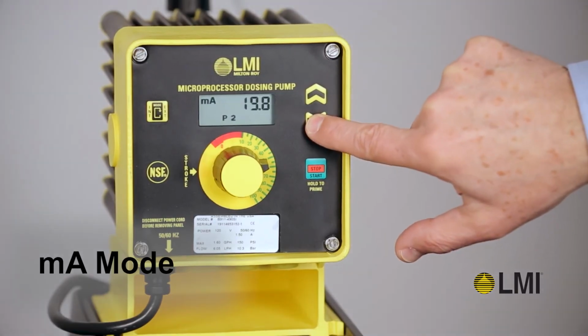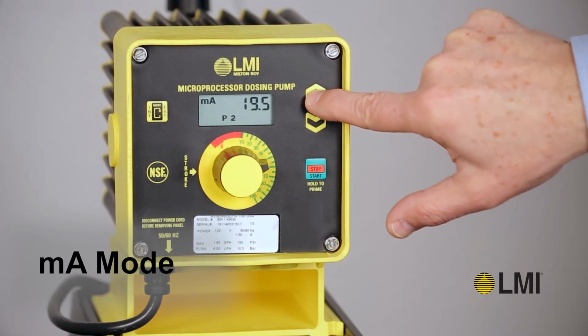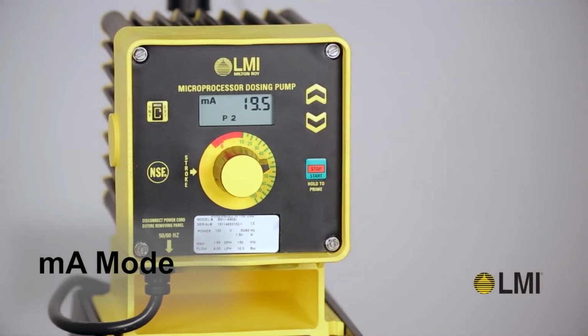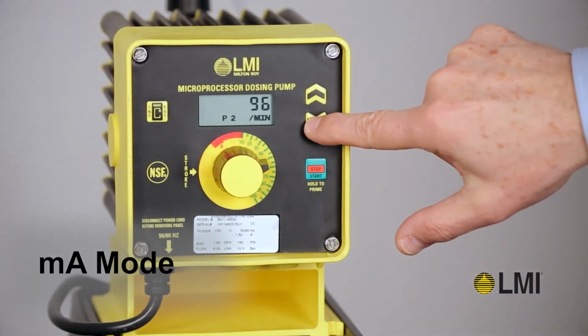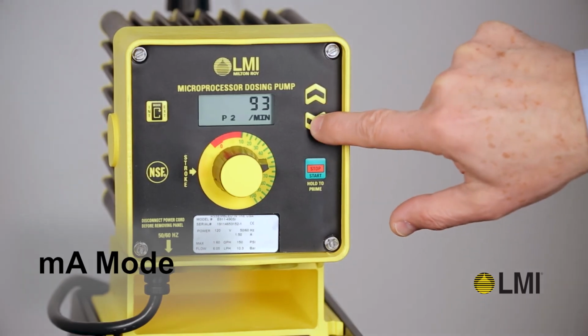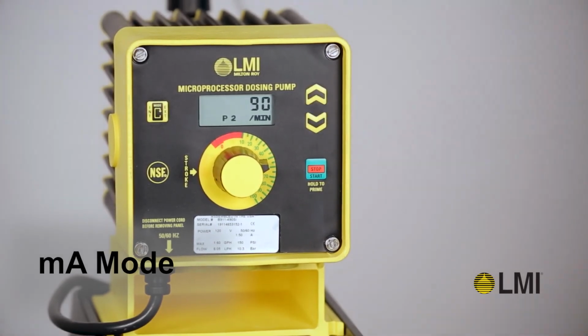Now input the milliamp value for P2 using the up and down arrow keys. After a brief pause, the strokes per minute for P2 will appear. Next, input the desired strokes per minute value for P2 by using the up and down arrow keys. Press the start/stop key. The pump is now ready to receive external signals. The parameters to make these changes will appear for only 5 seconds for each selection. Thus, the value must be adjusted quickly.